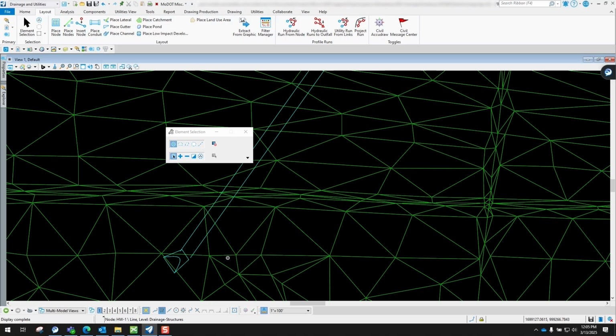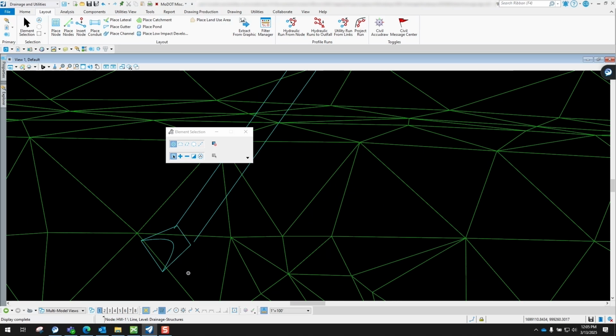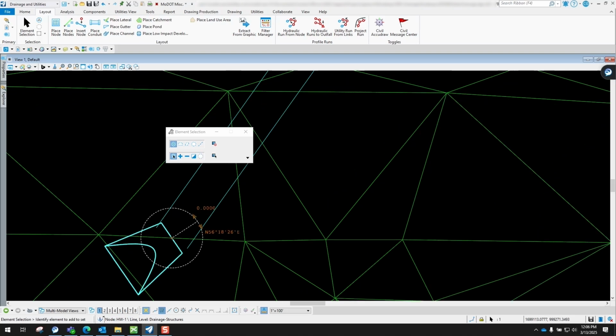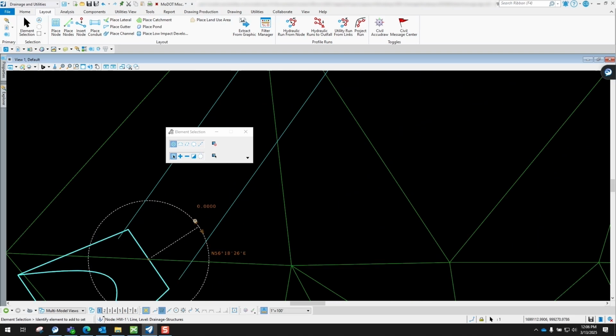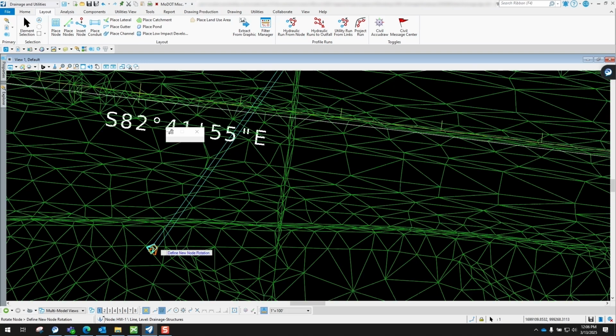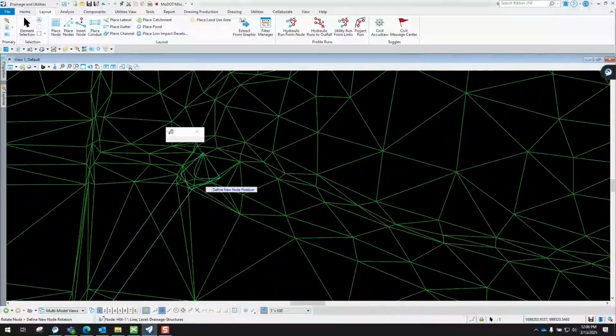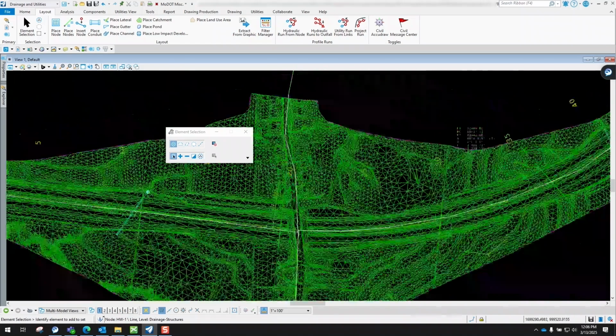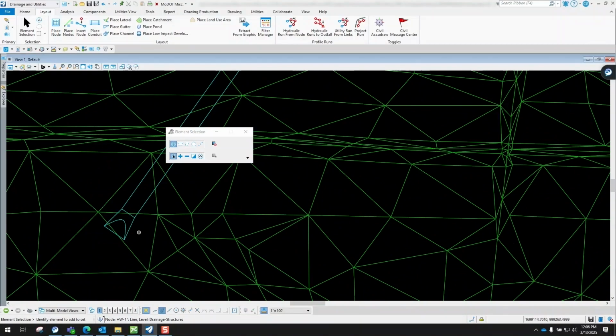Now, once it's been moved, of course, you may need to come in here for your flared in sections. You will probably need to rotate those also. We've discussed that in a previous video, but just to review it again, all we need to do is left click on the structure. You see these little arrows right here. Grab that. And then what I will do is just simply zoom up to this other end right here and snap to this other flared in section. And now it should be rotated correctly, as you can see right there.